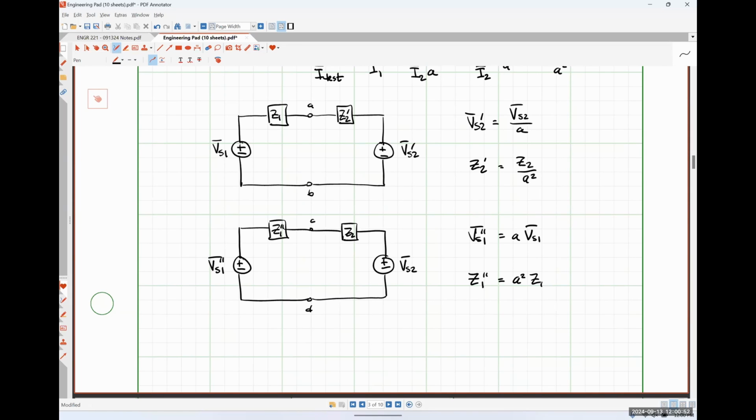They're an interesting thing and they're definitely used in industry, but as a very, very brief thing, an auto transformer is what you get when you have a single coil, but you tap it in multiple locations so that you have the same flux flowing through different parts of the same coil. And you can make that behave like a transformer as well. A three-phase transformer is just three single-phase transformers tied together in either a delta or Y configuration. So it's harder to draw the damn thing than it is to actually understand what's going on.